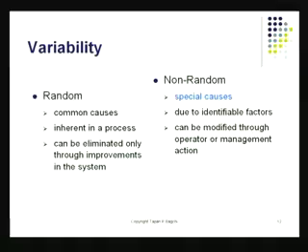The role of control charts is to help us remove all those factors that might impact either the accuracy or the precision of the process, to make sure what we produce can be sold without any problem at all, or used in subsequent processes. Where do these variations come from? They come from a variety of different causes, which are large in number, but individually produce very little impact.